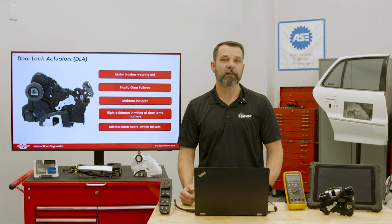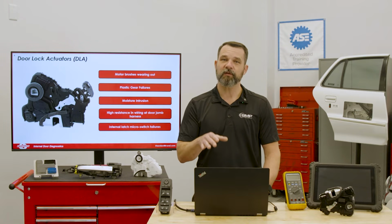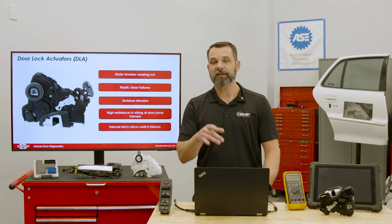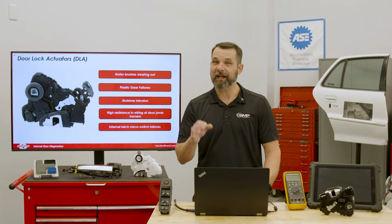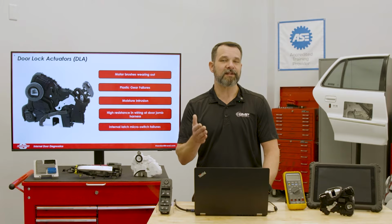We've done this with fuel pumps for years, and that can give us some clues every now and then, but also checking for voltage at the actuator while commanding it with a scan tool or the switch itself. And it's a good idea to wiggle test the door jamb harness for any intermittent power or ground issues at the same time, as this is actually far more common than you might expect. And then, of course, scan the BCM codes.